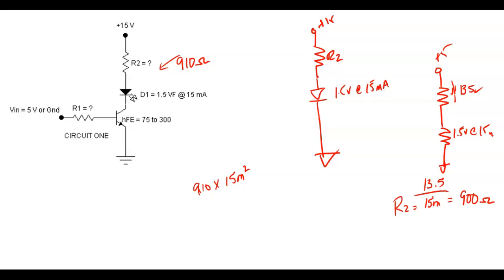Okay, now I know this guy over here. I know the voltage drop across this guy right here. I know the voltage drop right here. It's 0.7. Here's the second series loop right here. So if that guy right there is dropping 4.7, then I know this guy right here has got to drop 4.3. I know, right? Because of Kirchhoff's voltage law. But I need one more thing. I need I. I know I in the collector, but I don't know I in the base yet.